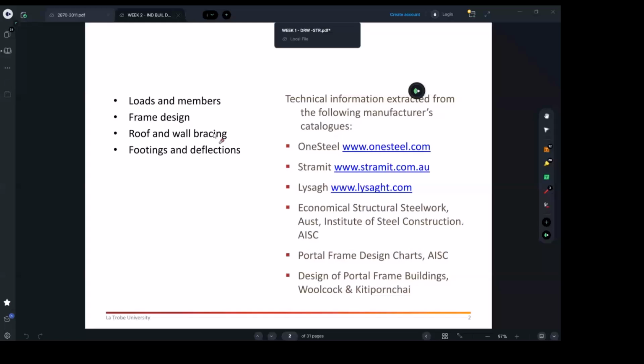The example I just gave you now was the block wall. The block walls I showed you in the library projects were there to resist lateral loads. If for whatever reason they were ignored and not built, and they were assumed to be just an architectural feature wall separating 2 rooms from each other, then that would add another 2 weeks to your bill to fix the missing walls. So if you understand the frame design, that the block walls were actually there as a structural guide to stabilize the building from lateral loads, then you will build them in parallel with building the columns, or you must build them before building the slab. It's too complicated to do it after.